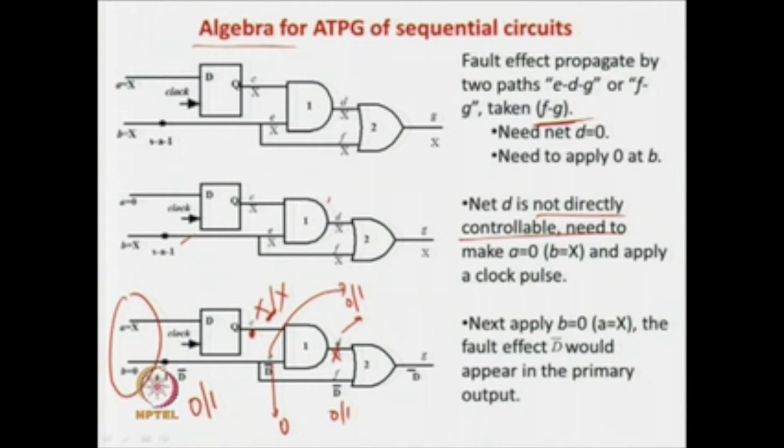So, what is the output of D at fault? If the fault is not there, normal, the output will be a 0, because if the stuck-at fault is not there, you apply a 0 over here, so you will get a 0 over here. So, by default your D is going to be a 0, okay, and other things are fine. Now, if there is a fault, then it is stuck at 1. So, you are going to get a 1 over here, and this is a x, because we are not applying anything for the time being, just assume. So, it is 0 and x at D if you are not controlling this, for the time being, just assume, correct.